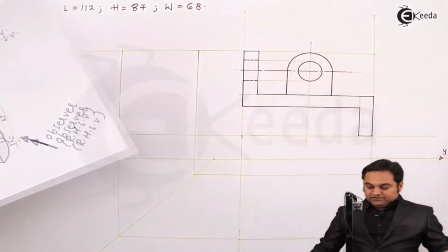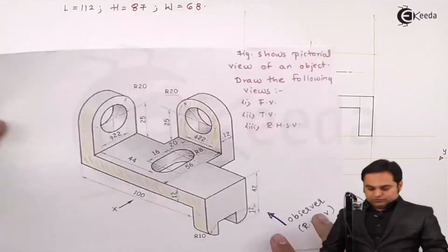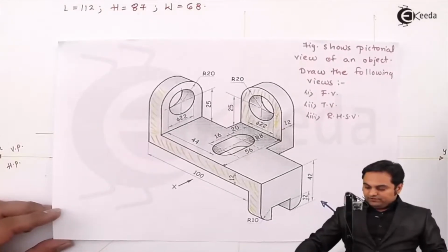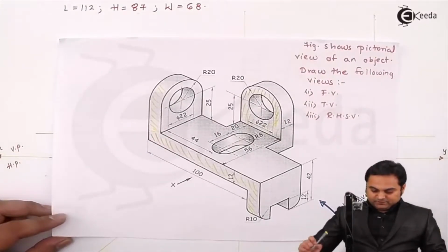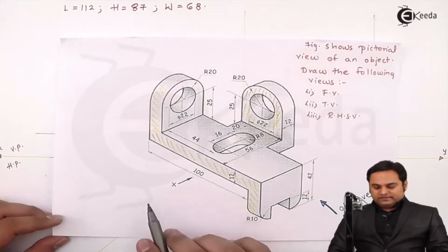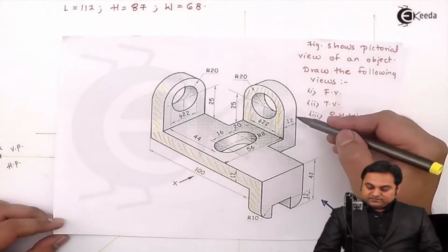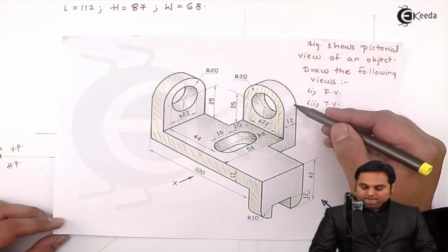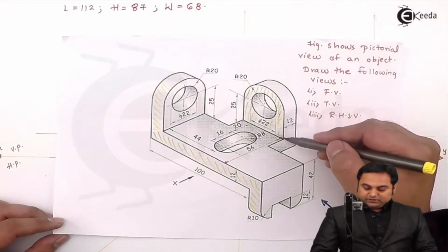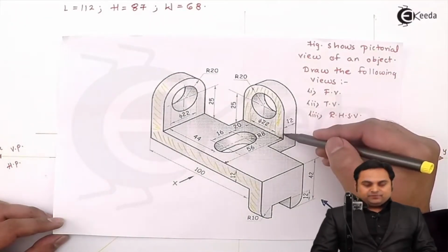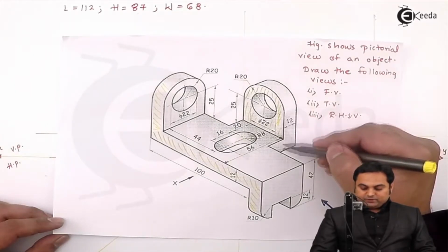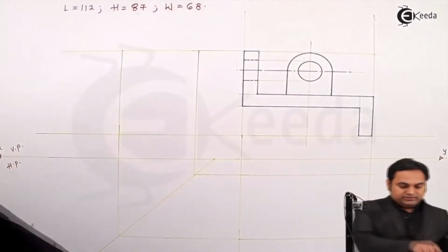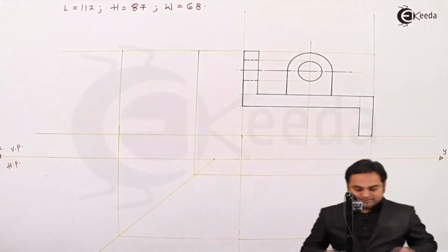I have completed the visible part, and for the hidden portion, if we look into the diagram, from the front, that is along x direction, this line which is behind is not visible, but a certain part of it is coinciding with this line. So the remaining portion in this block should be hidden.